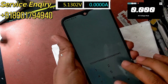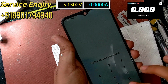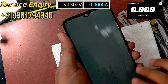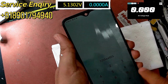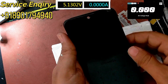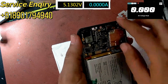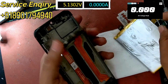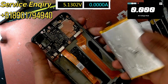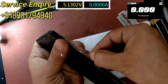Right, the screen is visible, the keypad is working, right? Maybe the battery saver is on, so that's why the brightness is low, right? But the customer had a pattern, so we, right? So this power IC is completely okay. As I told you, the fault comes from anywhere, but in this case the fault is the charging IC. So we remove it and check why the charging IC leaks. I will also tell you.